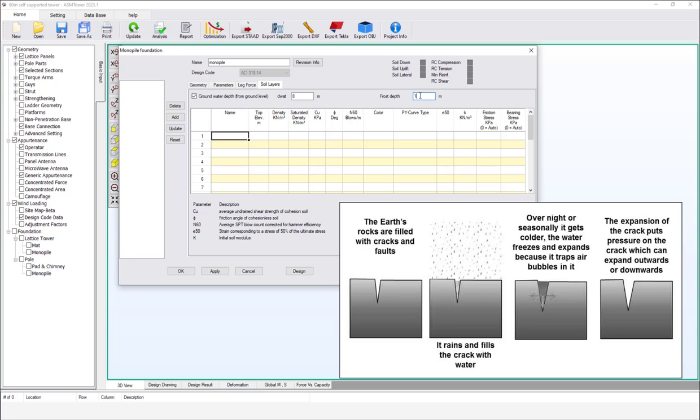In cohesive soil, when the water within the soil freezes, it causes an increase in the size of water particles and forms cracks within the soil. When the frozen water thaws, these cracks may be filled with air, resulting in a reduction of the soil's friction capacity. At the frost depth, the soil capacity is typically neglected in calculations due to the compromised soil properties caused by the freezing and thawing process.